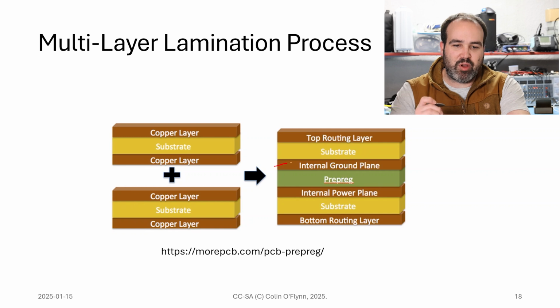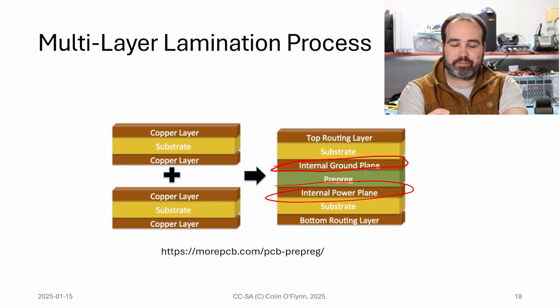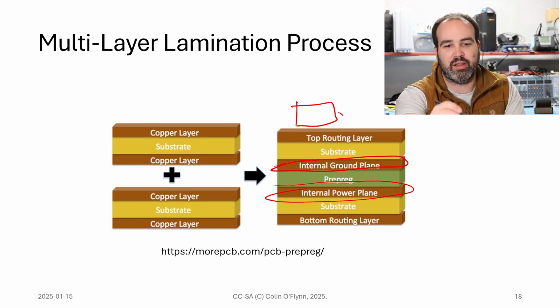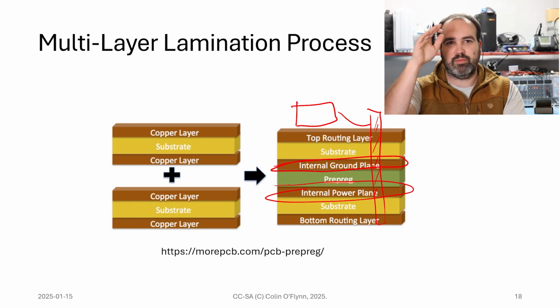When it comes to multi-layer boards, we've brought this up a few times without fully explaining it. Just trying to go back to this stack up here, right? You have like a plane. So I have this power plane or ground plane here and this power plane here. And the idea here is that if I have my FPGA on top, or my big part, or any part really, it makes it really easy to then just go down to a power plane without having to route a million traces around. And this is going to make life easier. It's going to make our impedance lower. It's going to make our emissions lower. So it's very nice when you can to have these planes and pours.